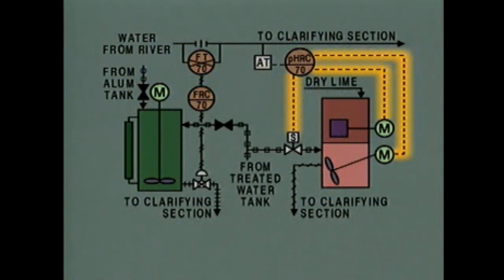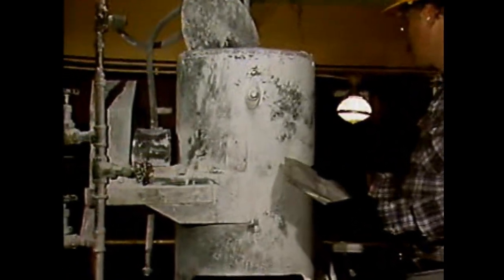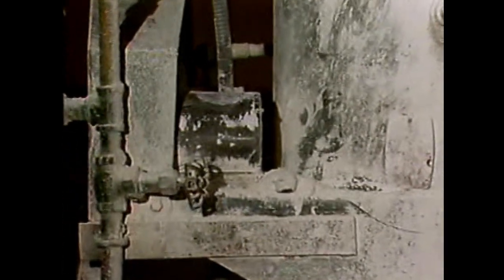Finally, we could trace the electrical conduits from the lime system to the pH recorder controller and back to the analyzer transmitter, looking for damage that might indicate an electrical signal problem. After the components that could be causing the problem have been identified, the components can be inspected to locate the problem. In this case, the problem turned out to be a bad electrical connection at the lime shaker motor that kept the motor from operating properly. The P&IDs helped us focus our troubleshooting on the components in the system that could be associated with the problem.